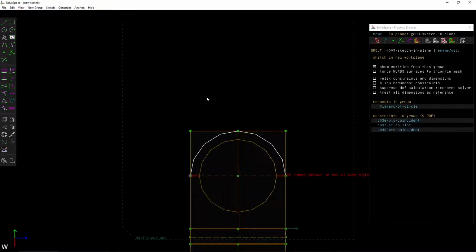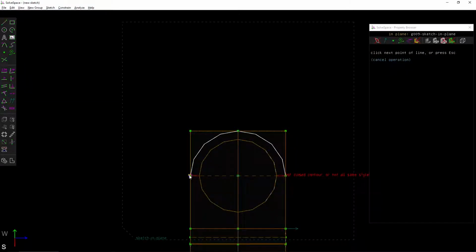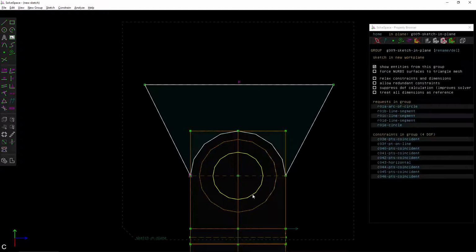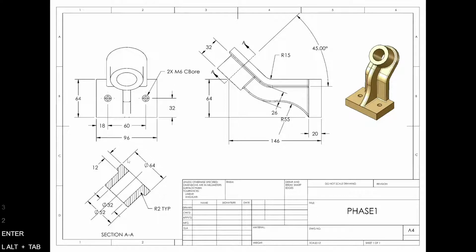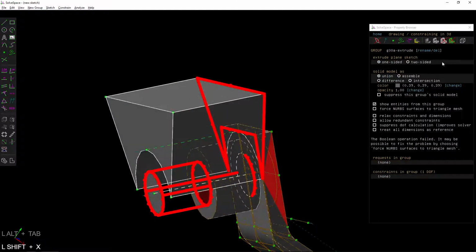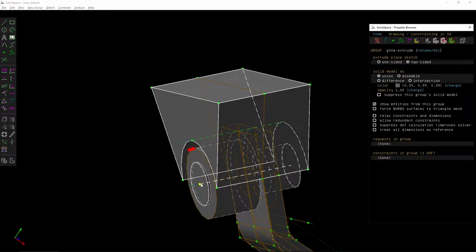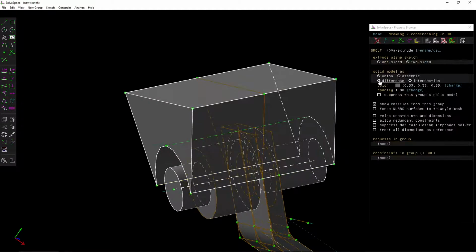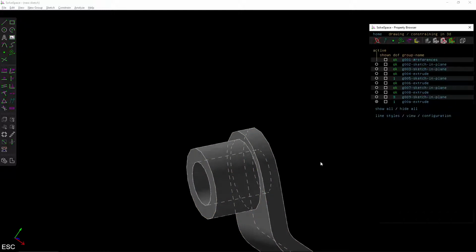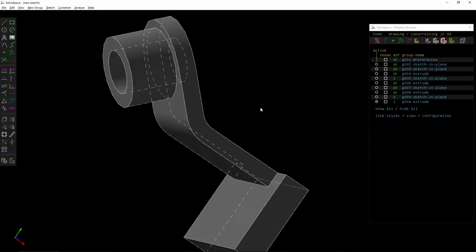In order to make this cut out the corners, I need to make this a shape. So I'll just put some lines here, completely random, and an extra circle for the hole. It's diameter 32, yes. Extrude this, two-sided, stretch it out and make it a difference. And now I have the cylinder shape.